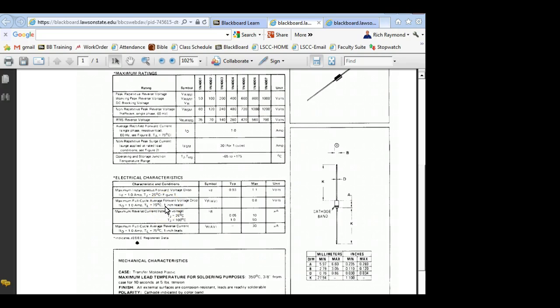A lot of people don't understand that the length of the leads determines how fast the device can get rid of heat. The longer the leads, the longer it takes, because basically most of your sinking is done by the printed circuit board itself. So if you have these big old long leads, that's going to hurt you as far as getting to your sinking source faster, right?